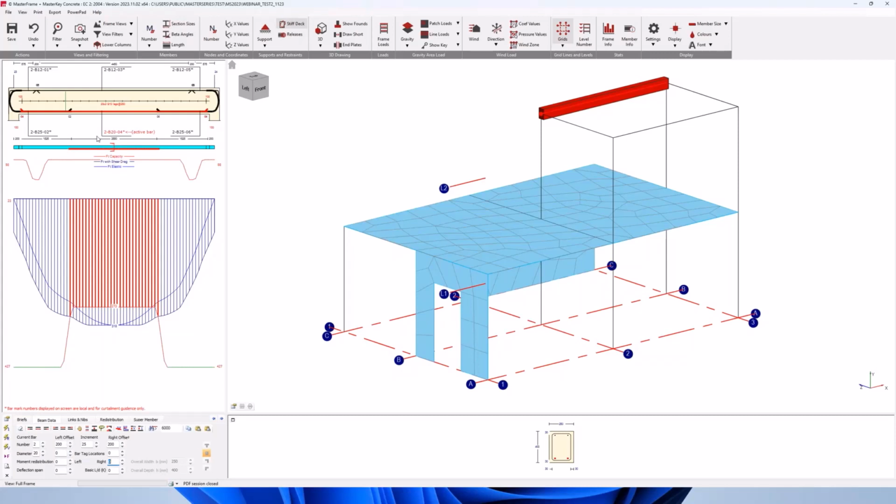So we can see that now the middle portion of the beam is failing. So we definitely need more bars. So I'm going to add one more bar to this bar set. I simply click on the number of the bars with my left mouse button and increase the number from 2 to 3. And now you can see it works.